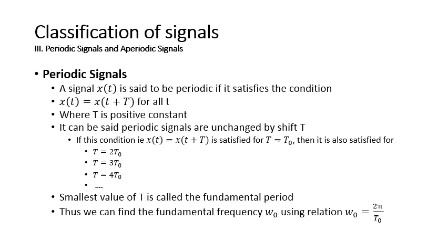So in case of periodic signal, continuous time periodic signal, we say if x of t equals x of t plus the capital T, right? You understand this small t basically signifies that it is a time domain signal, and because t has continuous values, it says that the signal is continuous, right? So continuous time domain signal. So if x of t equals x of t plus the capital T for all values of this t, then we say that this signal is basically a periodic signal where capital T is a positive constant, right?